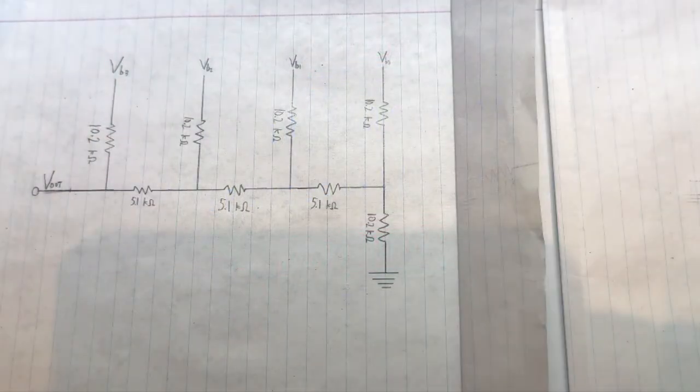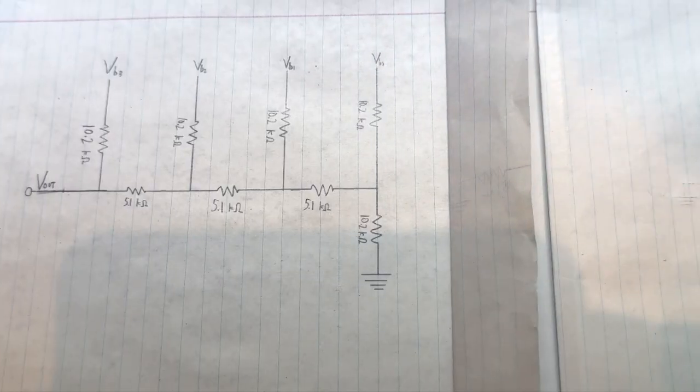So first, understand the DAC. We're going to look at the total resistance of the circuit. This can be done with Thevenin's equivalent circuits. To make it easier to understand, I'm going to be explaining this on a scaled-down version of the DAC. I have a 16-bit DAC, but to explain the concepts, I will be using a diagram of a 4-bit DAC.